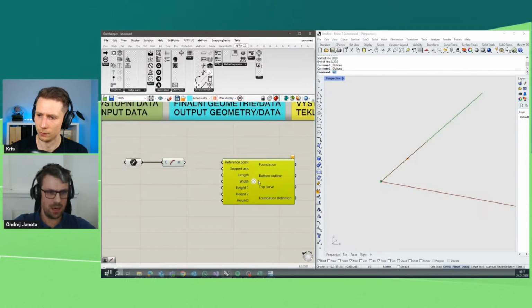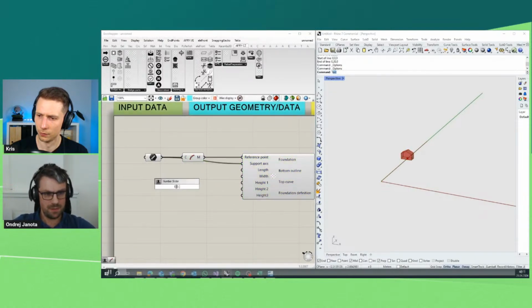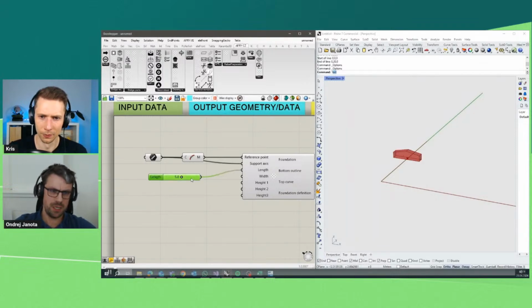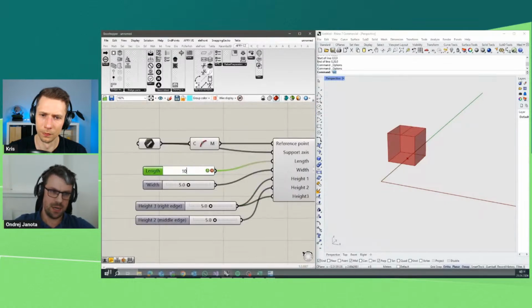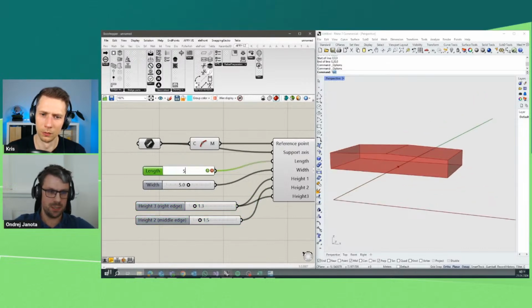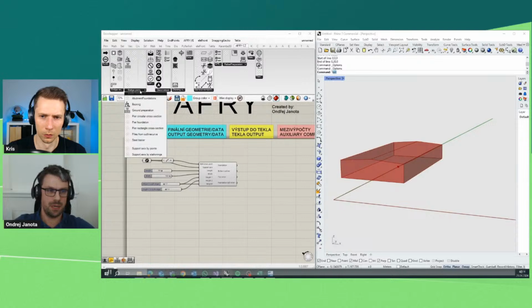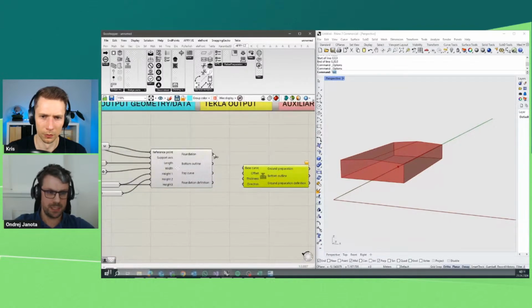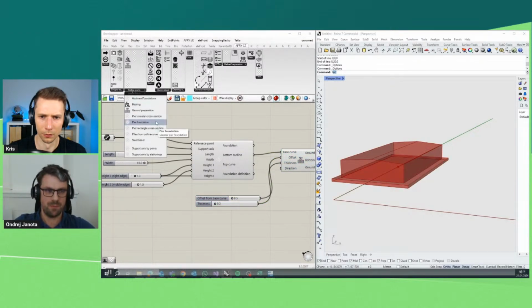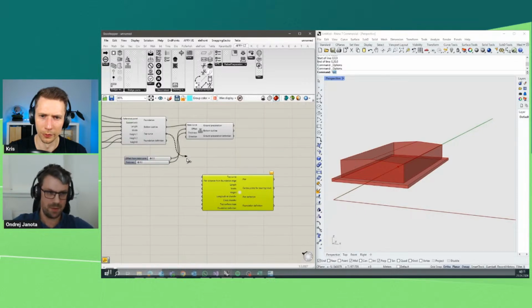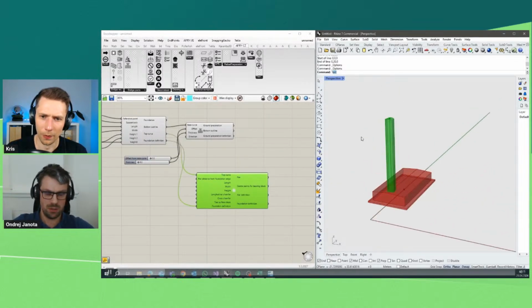We use, as I said, our own library, and the benefit here is that if we create the geometry of, for example, a pier foundation, we don't just create the concrete geometry, but we also stick the reinforcement rails and shapes together, because I believe that if you are a bridge designer and you have, let's say, 5-10 similar pier foundations or piers, you should always go with the same reinforcement scheme. Not the reinforcement itself, but the shape of the reinforcement should be the same, because it's one office, and you know how to calculate all the things inside.